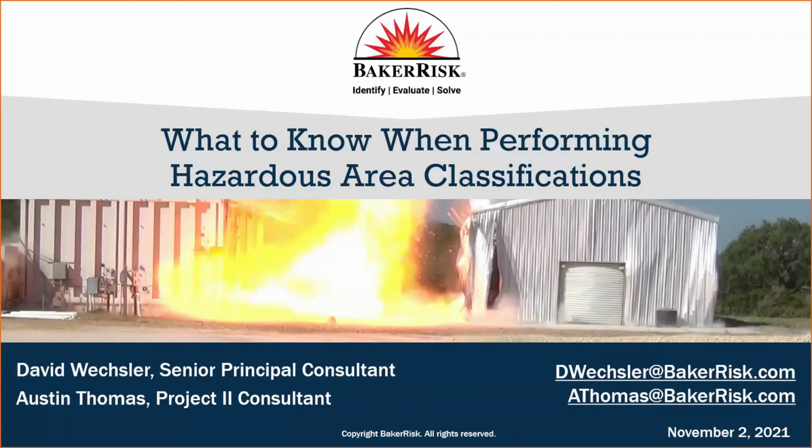So for example, if you're dealing with a combustible dust and you could locate the areas of potential release in one far removed area of that building, that may have less of an impact. It's the conduit area between the two buildings a farther distance away. However, if it's a flammable liquid or combustible liquid source, which could spill and move to that other location through the common breezeway area, that represents a different set of conditions. So I think it's important that you consider those conditions on the merits of each and come to an appropriate conclusion. And again, if you need help, Baker Risk can probably help you with that.